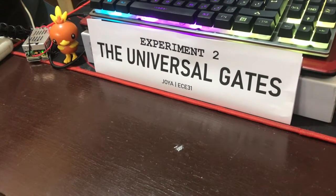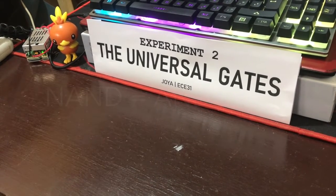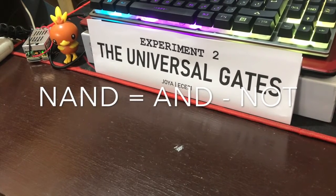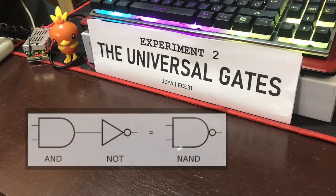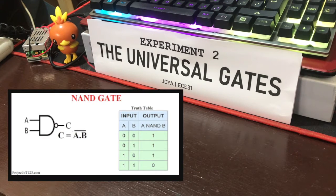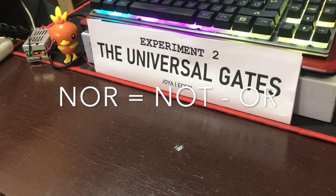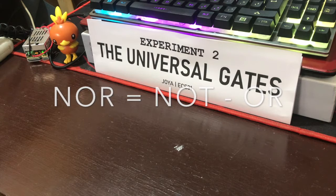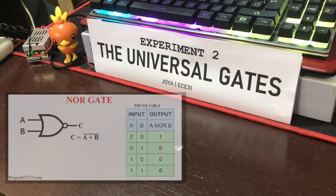The universal gates are essential since they are the most widely used type of digital logic elements. This is because they offer numerous advantages over simple gates considered earlier. The term NAND is a contraction of the expression not AND. A NAND gate, therefore, is an AND gate followed by an inverter. The NAND output is simply the complement of the AND output. The term NOR is a contraction for the expression not OR. Therefore, a NOR gate is essentially a circuit combining the logic functions of an OR gate and an inverter.